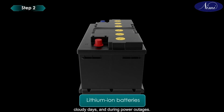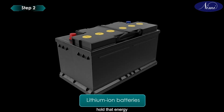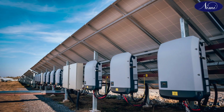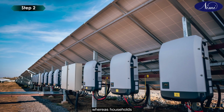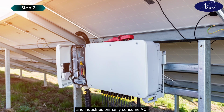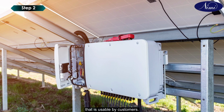Solar panel companies prefer lithium-ion batteries because they can store more energy, hold that energy longer than other batteries, and have a higher depth of discharge. DC/AC inverter capacity. Solar panels generate DC, whereas households and industries primarily consume AC. Thus, inverters convert solar energy into a form that is usable by customers.